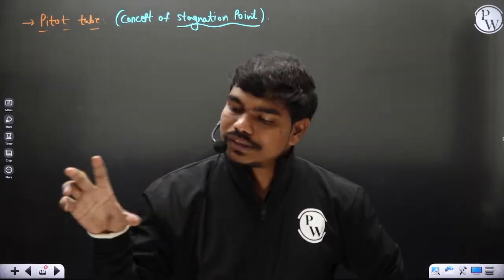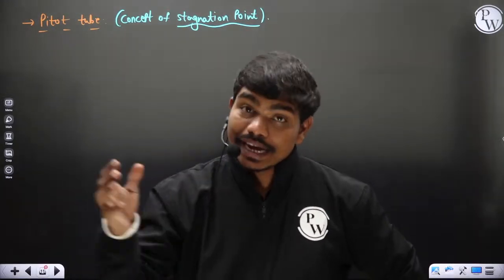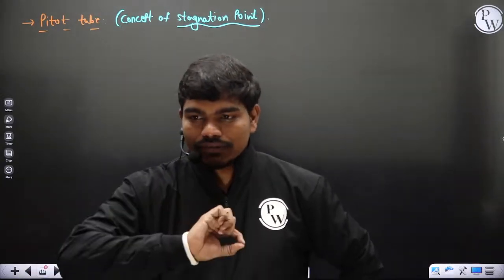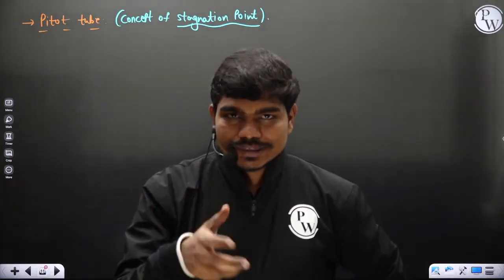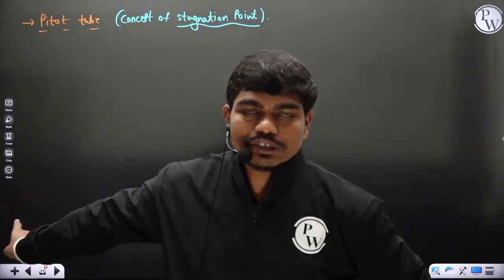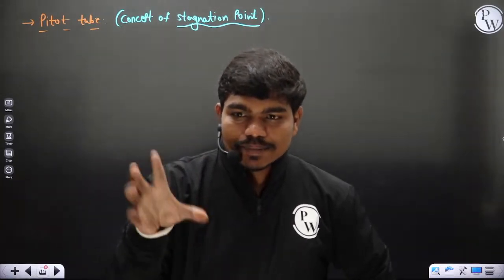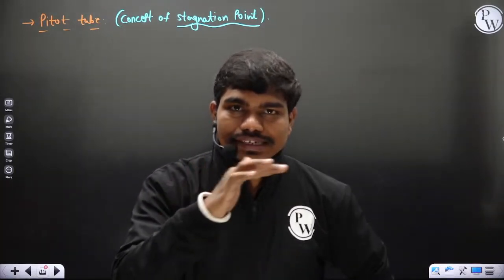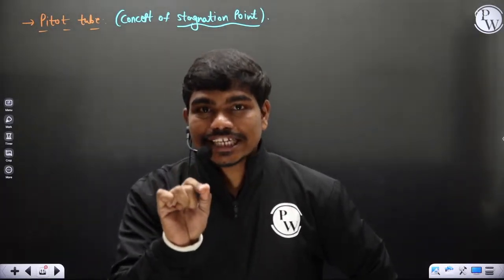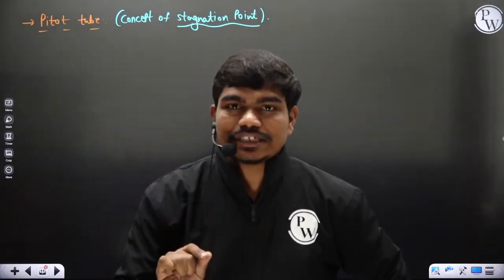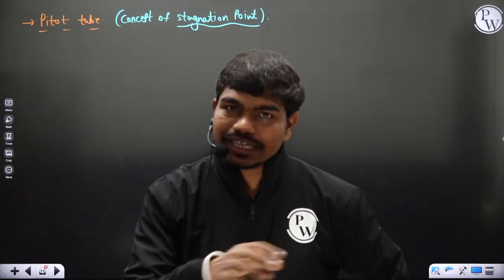Yes or no? Whenever the fluid passes through a pipeline or siphon, this cavitation issue is very highly present in siphons, and in pumps. When fluid passes through a pipeline or siphon or any device in general, there could be certain pressure changes in the fluid, like in the case of orifice and venturimeters. When the pressure is decreasing, if a limit comes where the pressure reached by the fluid is the same as the saturation pressure corresponding to the atmospheric temperature, then the fluid starts generating bubbles. And these bubbles are very dangerous, they can block the complete flow.